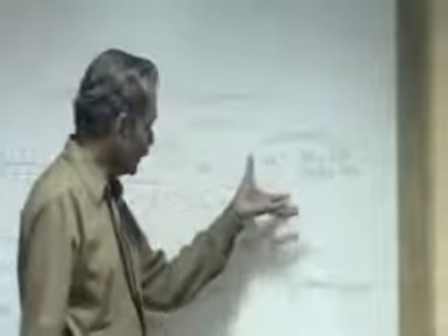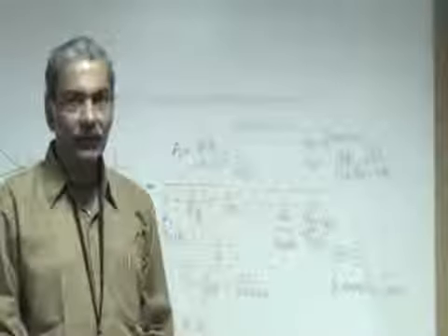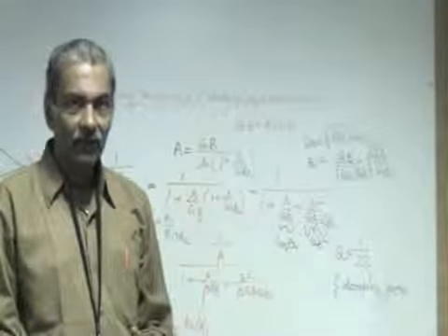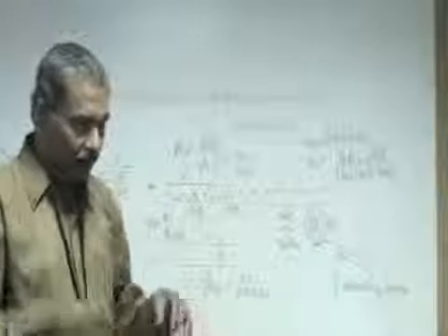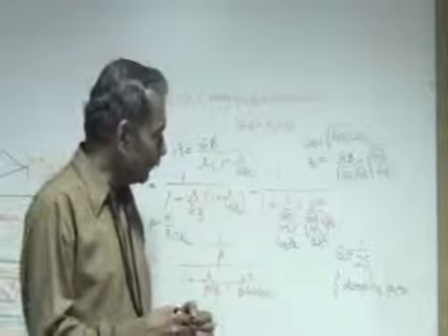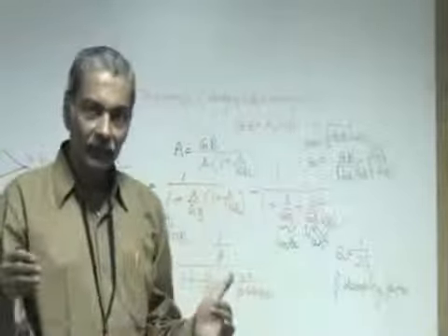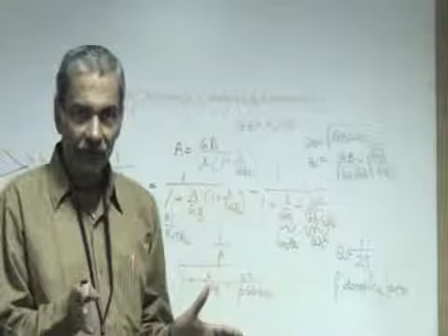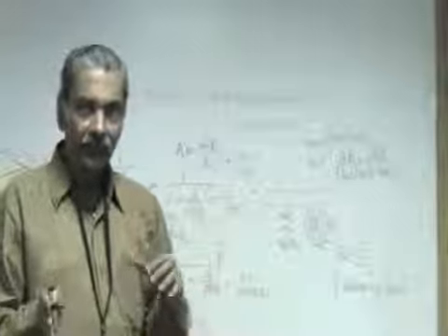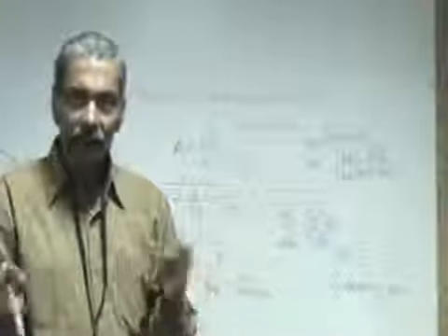Now that we know that, Q of this system can make it very transient and noise dependent. When a step input is given, it will start ringing, and the ringing frequency will be close to the natural frequency of the system, and Q is going to tell us how many such peakings will occur in the ring.